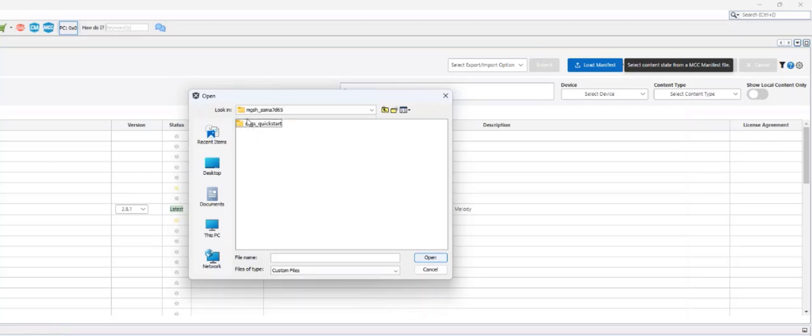Load the manifest file is what you're going to use to set the packages that you need to download, as well as the versions. So you go to Quick Start repo, go to firmware, go to the .X directory of the combination of display and board you need to use.